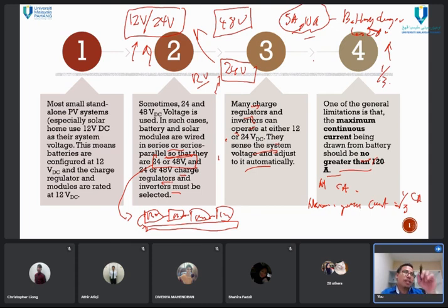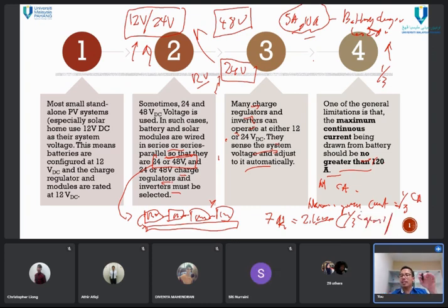Please follow. You can see if you buy the lead acid battery, deep cycle, the black one or the green one, GP brand for example, if you Google, then you will see they write almost 1/3 of the rated capacity. For example, if 7Ah, I think 2 point something, they say. Maximum less than 1/3 capacity of the battery. So this is the maximum charging current.